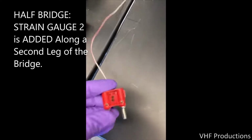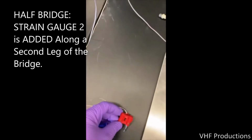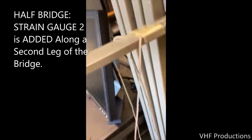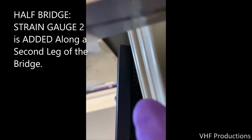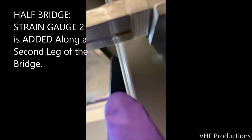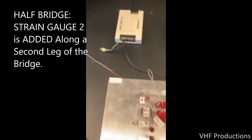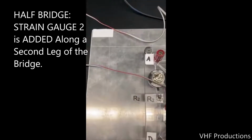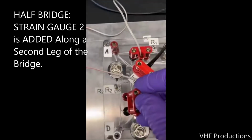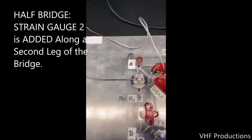In the second configuration, we will take 2 strain gauges and input them into the circuit. In the first case, we're going to use the same strain gauge on the top surface of the beam that goes into tension. And we're also going to pick a second strain gauge that's mounted on the bottom side of the same beam, directly below the first strain gauge on the top, and oriented in the same direction.